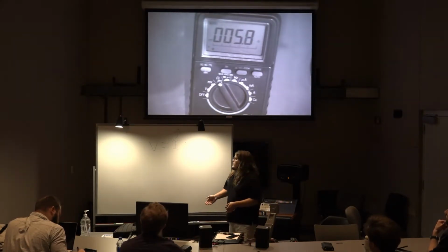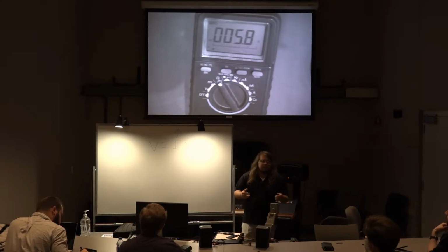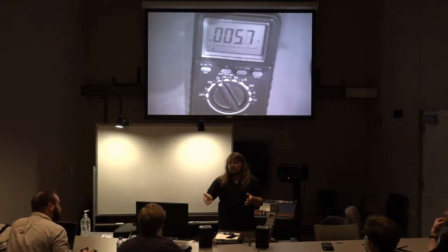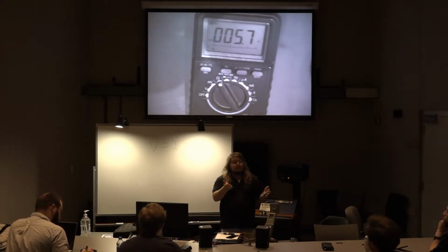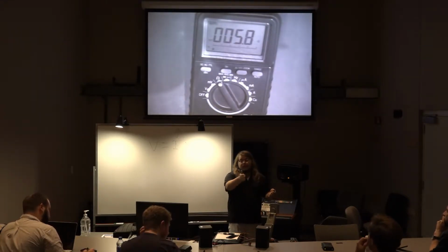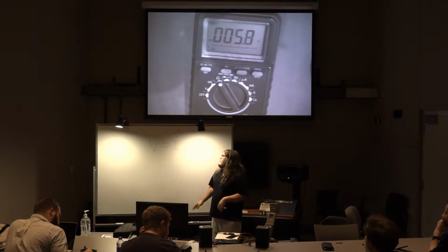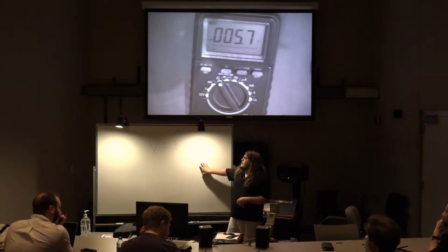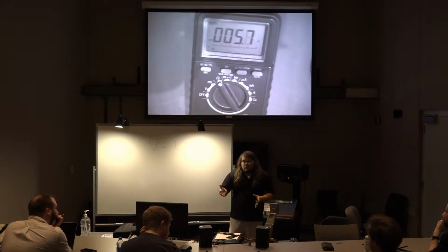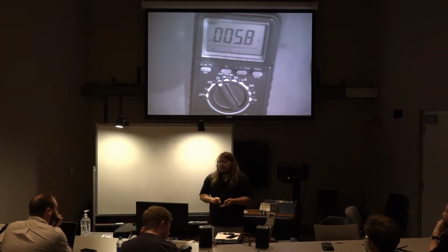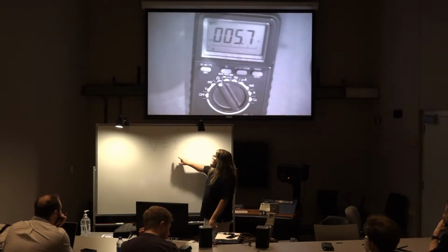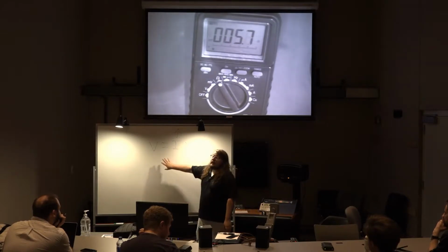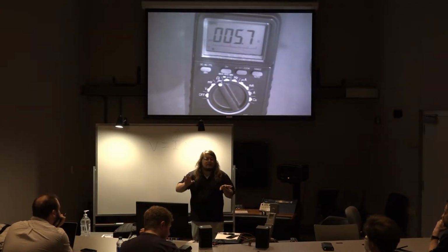And if we looked before, you also intuited that when we added the 2 speakers in series, the resistance went up, right? We observed a drop in voltage across each speaker. So the interesting dynamic here is, depending on how we connect our speakers, series, parallel, or just one speaker by itself, we're observing a couple of things changing. The current and the resistance, and in fact the voltage dropped across each speaker.